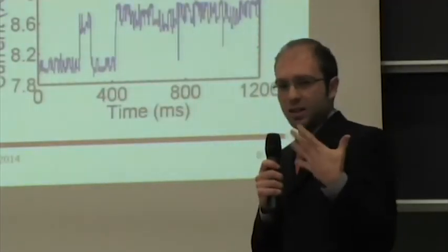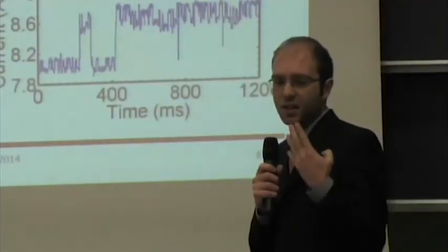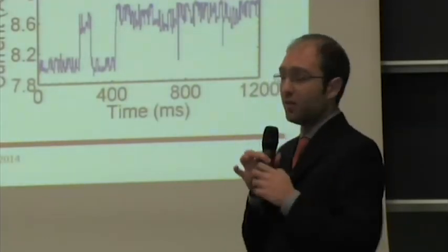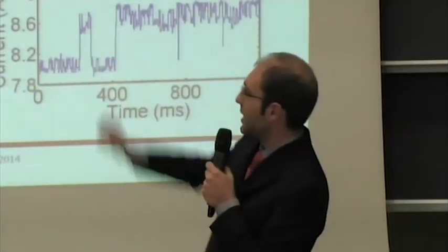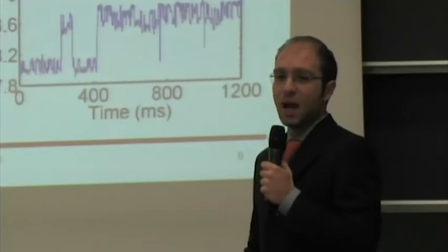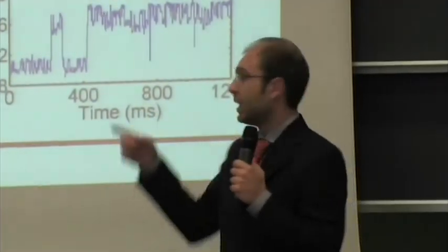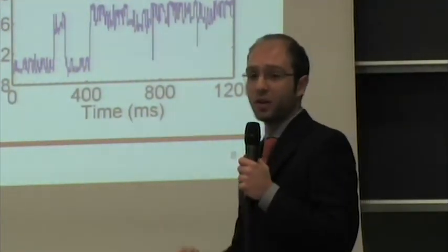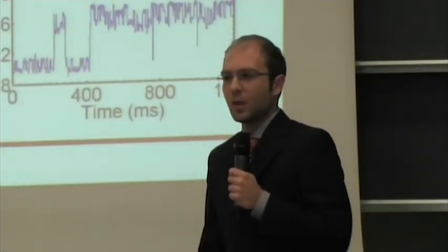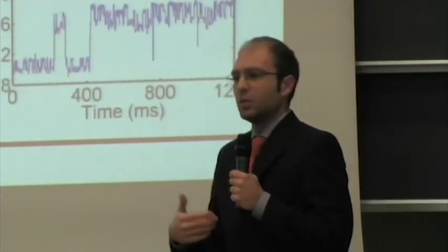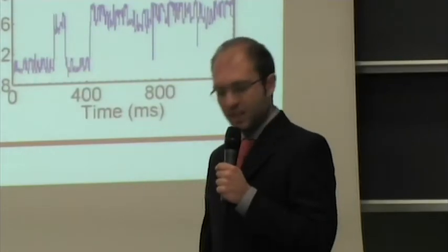Basically, we repeated this experiment for 4 different reset conditions, namely 4 different reset voltages, where the reset voltage is highlighted down there, and is the maximum absolute value of the voltage during the negative voltage sweep. And that's a very important parameter, which can be used to define different high resistive states.